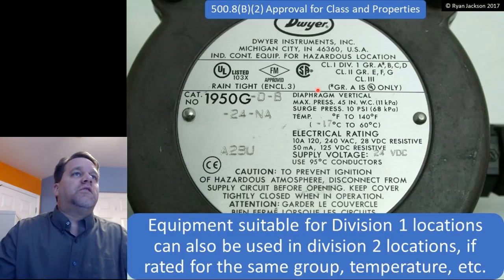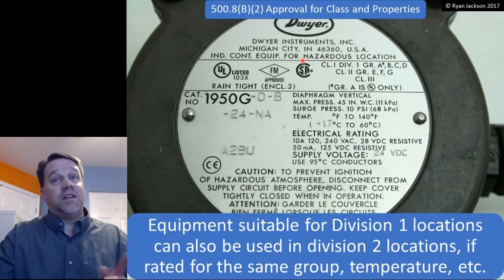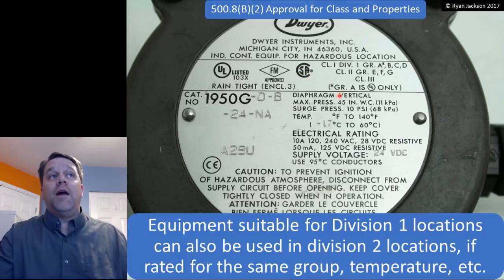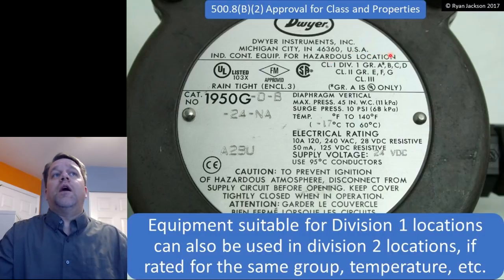So this piece of equipment says Class 1 Division 1, Group A, B, C, and D. And the little star here says that Group A is UL only, as opposed to CSA. So in other words, in Canada, Canadian Standards Association, I can't use this in Group A. But in America, UL, I can use this in Group A.